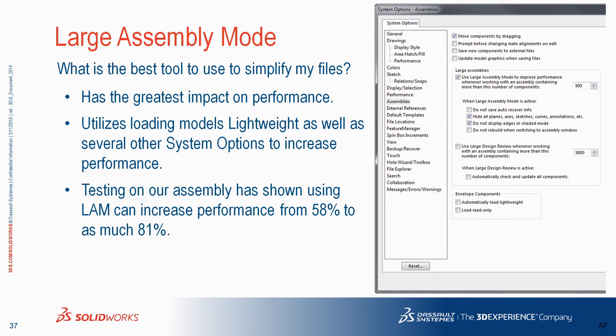So, large assembly mode, it does work. When it first got introduced years ago, it didn't. But they fixed that since then. A lot of times when large assembly doesn't seem to work for you, what we have found is dismissed error messages are the culprit. You're not getting the warnings that you should be getting to let you know that the information that they need for pulling up the models isn't there or isn't available or is not in the right form at the time.